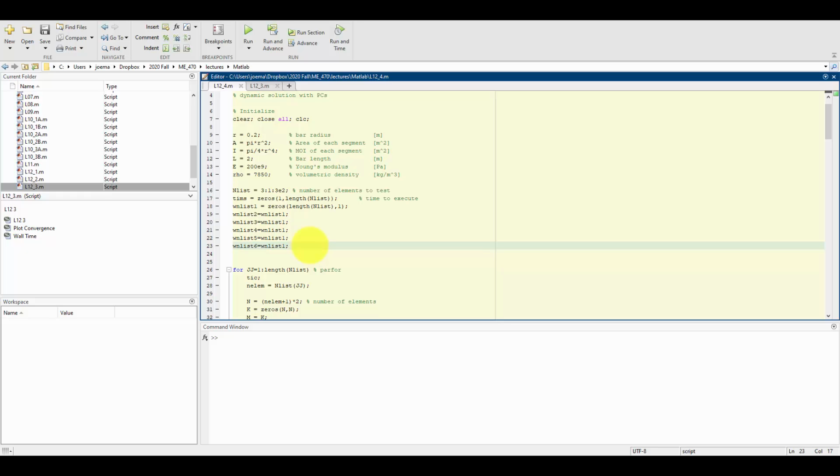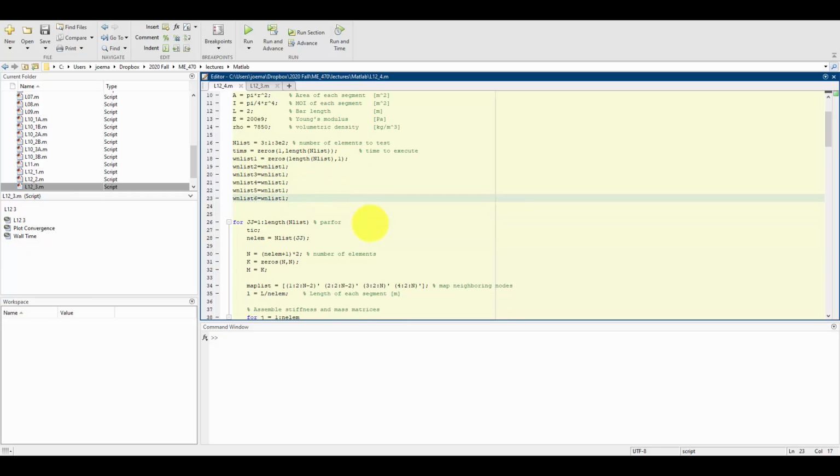So I just want to be really cautious that I'm going to get good quality results, so I'll track the first 6. Probably even tracking just the first 4 and looking for convergence would be enough, but this will make sure that we have good results. So I'm going to go up in testing from using 3 elements to using 300, and we'll see that we will get convergence definitely by 300, but we don't necessarily know that beforehand, so we will track that.